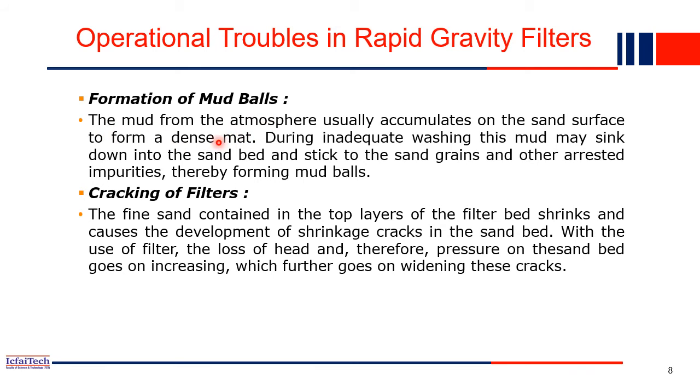The mud from the atmosphere usually accumulates on the sand surface. It forms a dense layer on the top. If you don't wash this sand bed, what will happen? The mud deposited at the top will form in a ball shape, and this we actually call a mud ball. That's why it is very essential to clean this rapid sand filter frequently, every day or every week.